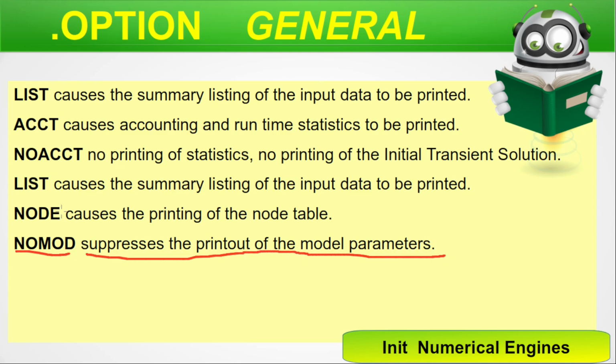Whatever options I'm talking about are regarding ngSpice, and from one SPICE simulator to another SPICE simulator, there will be similar options, similar commands. You have to check the manual for that, but the philosophy remains the same. So you understand the philosophy here for ngSpice, and then you can map it to any standard industrial EDA SPICE tool, whether it is a basic SPICE, PureSpice, accelerator SPICE, or FastSPICE. Anything, there will be such a set of options. Philosophically they will be similar to ngSpice, but there may be some changes in the text or something. So you understand the philosophy here, and you can port it to the actual VLSI world.